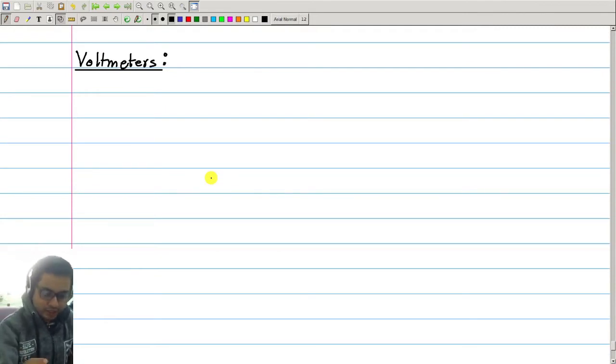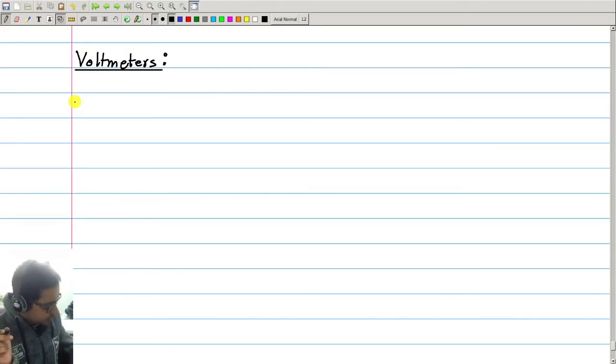Okay. So what we have seen is that PMMC, electrodynamic or MI instruments by default measure current. Their deflection depends on the current flowing through the coils. Only electrostatic instruments respond directly to voltage. However, as I was saying, electrostatic instruments are not used much. They are used mainly for high voltage measurements. But we can use PMMC, electrodynamic, MI instruments also for measuring voltage using Ohm's law.